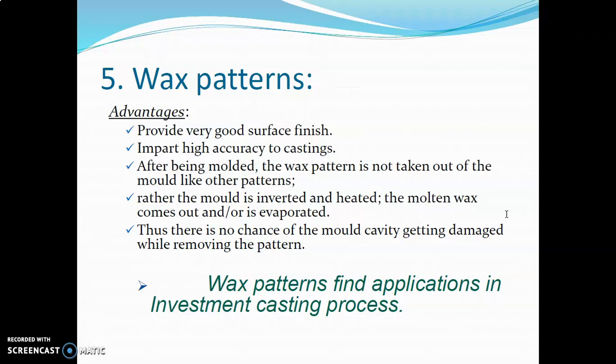So this is actually the biggest advantage, and due to this feature only, this pattern is very famous. Say we made a pattern with the wax material. Then we have placed each and every component, like sand, cope and drag, everything. Now, what we are doing is heating that whole thing, and the wax gets melted or evaporated and comes out from the mold cavity. So there is very little chance of damage to the mold cavity.